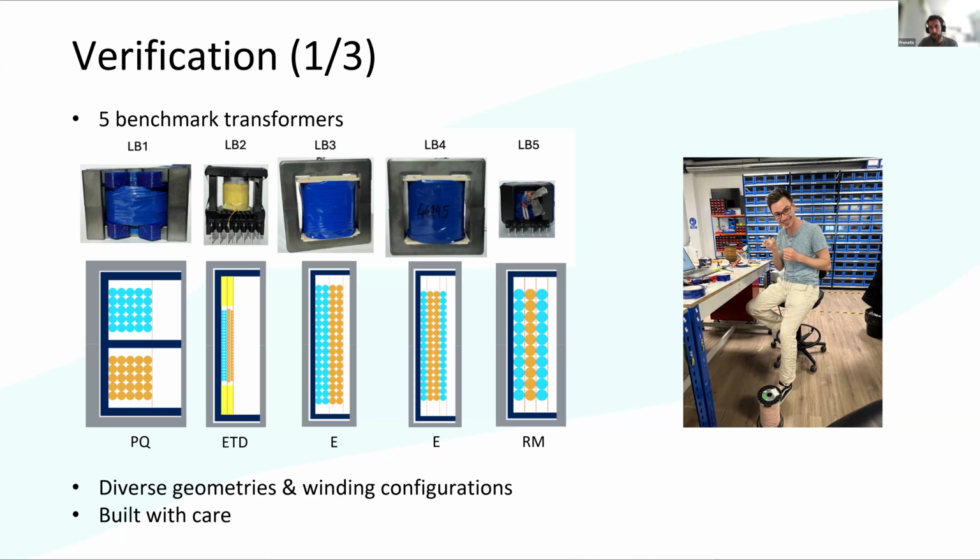There is one question that says, do you have any comparisons of leakage between a center leg air gap transformer and a three leg air gap transformer? No, we don't. But just look at the path that the field needs to cross in relation to the window height, if you have air gaps on all transformer legs.